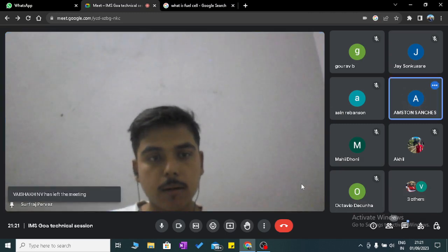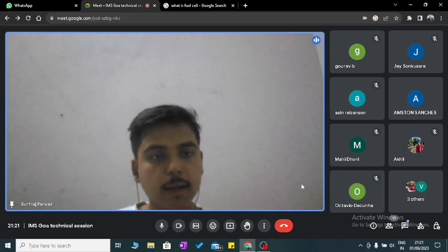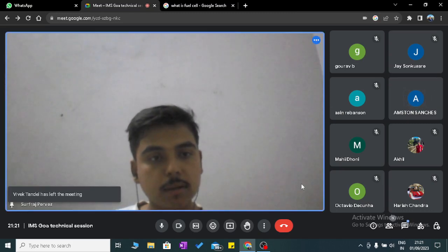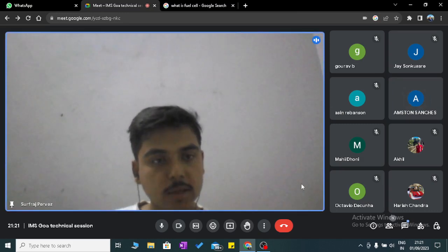Twist drill. Center drilling or something like that, right? If we don't drill directly with the twist drill, before using the twist drill we use something else, a smaller one, to center it. Okay, a center drill, I think, to make a small hole.